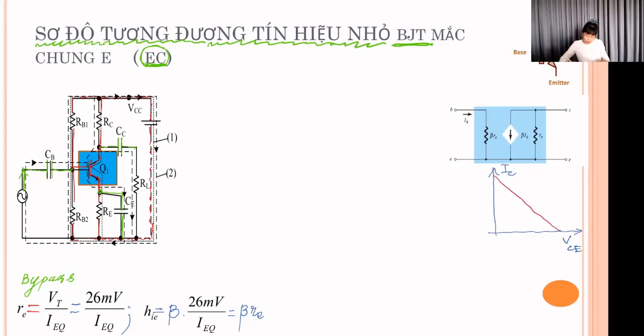And you have the one DC load line: VCC, and VCC divided by RC plus RE all the time. You should remember this. And the Q point here, this here is IBQ, and here we have the Q point. This is the first question, related to the red color.